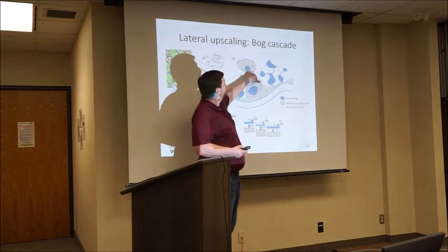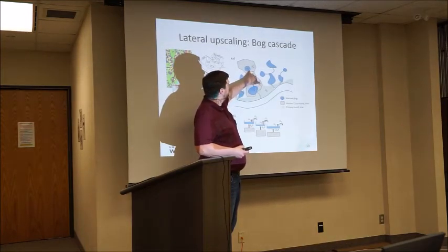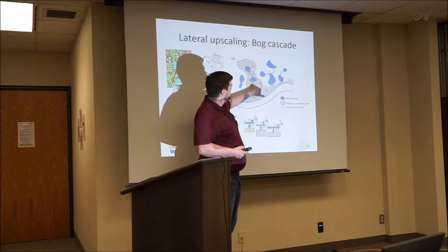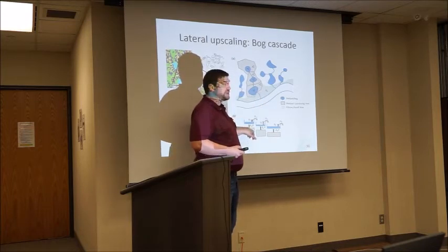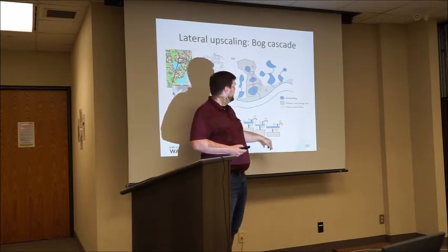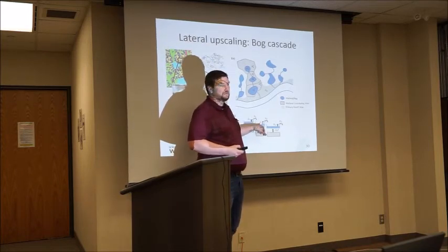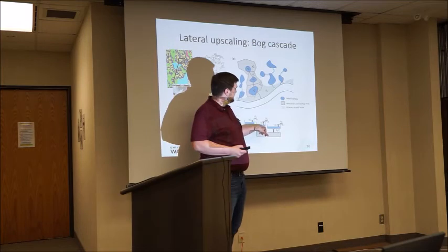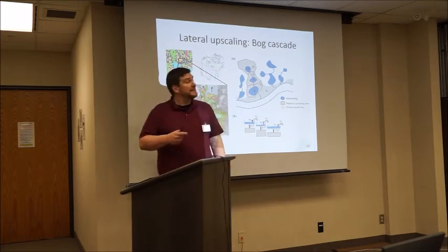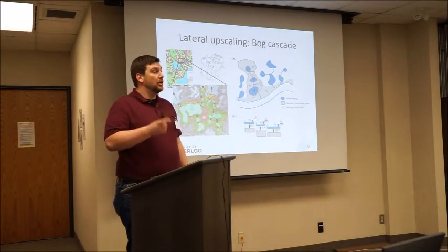Each of the bogs has a contributing area. Once this fills up, it overflows to here. This has a contributing area and overflows. And we can treat this in a pretty simplified manner. So this is a runoff area to fill up the deficit and then overflow. Fill up the deficit, overflow, etc. Now this is a very simple local model.